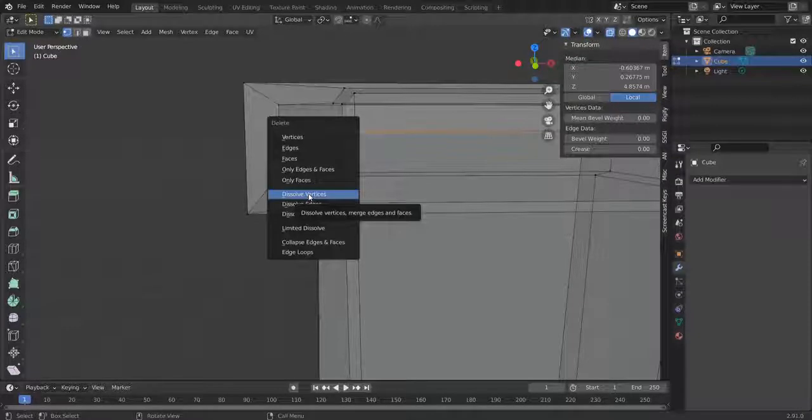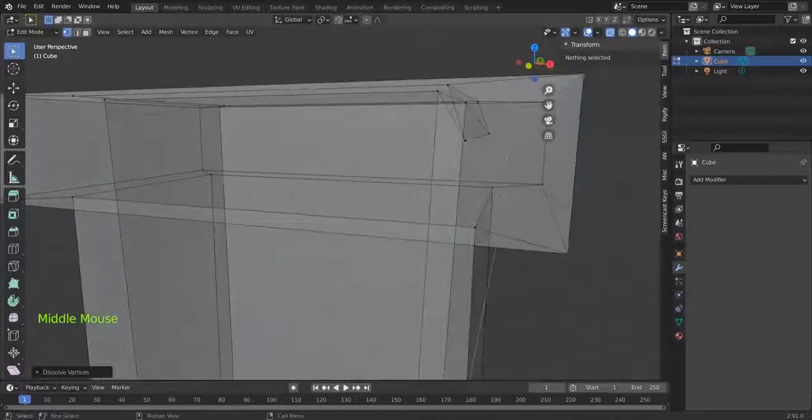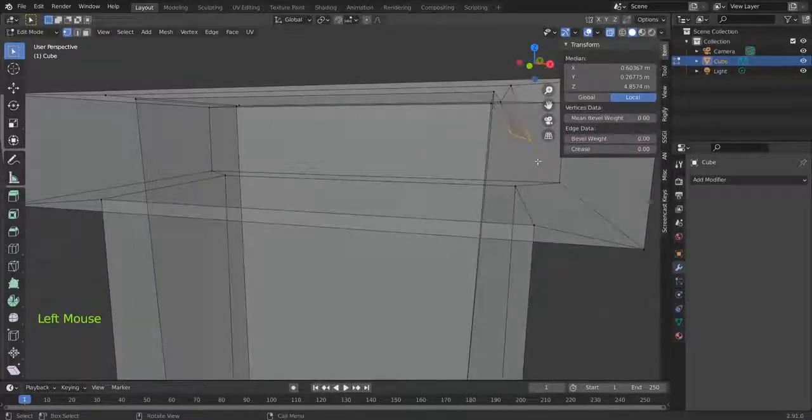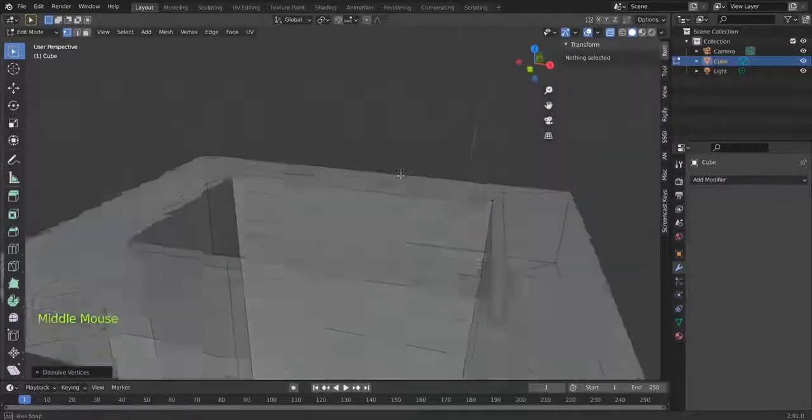The shape stays closed and whole but those vertices aren't there anymore. If you do delete, there will be empty space inside the shape. Okay, so we do dissolve vertices, and then we go to the other two on the other side, and we do also X and then D to dissolve these vertices.